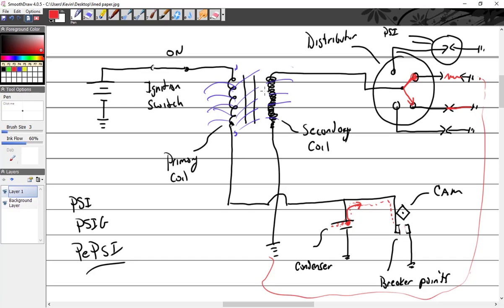So when you use that compressed air, it acts like it widens the gap. Yep. So it increases the voltage. Yes, it doesn't physically do it, but it's more insulated. You're packing insulators in there, so it just appears that it's wider.